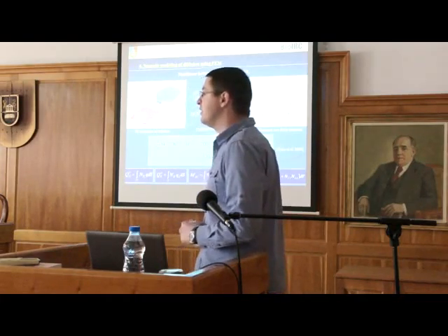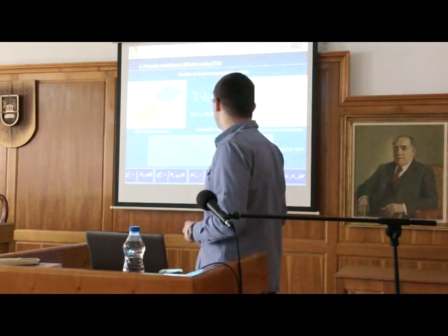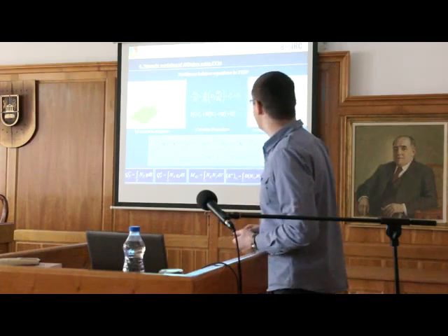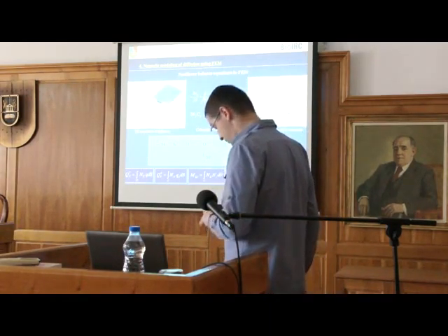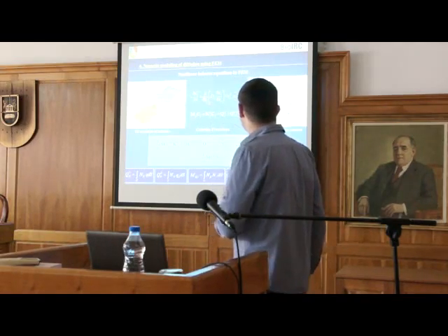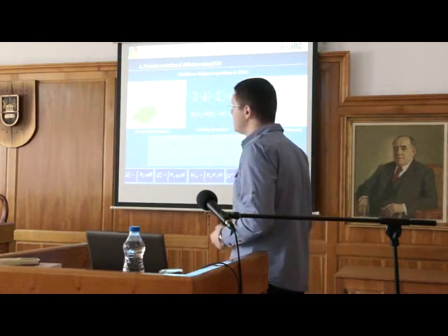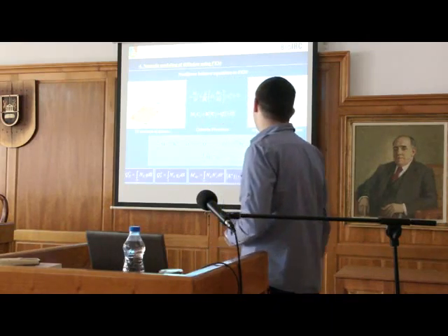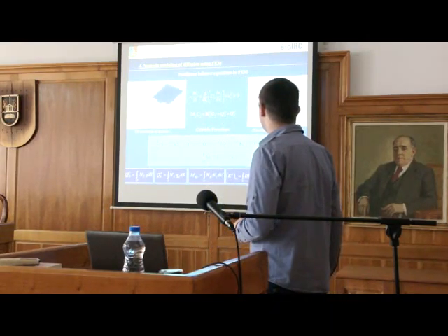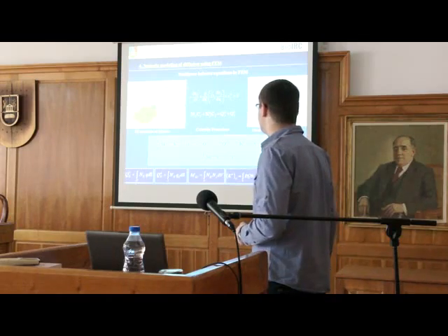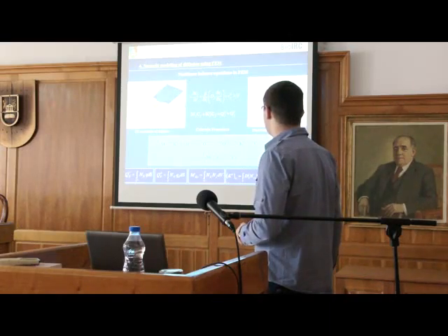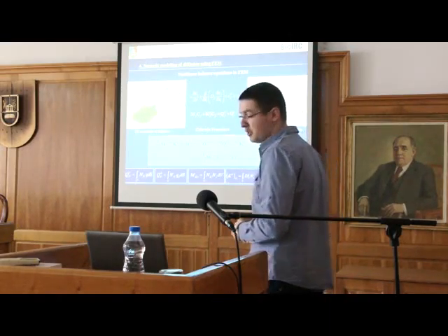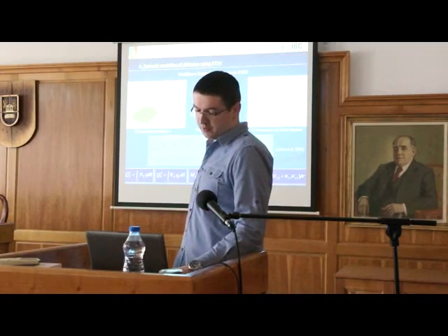Okay, we are using FEM. These are just some basic relations. So we started from the mass balance equation, and after that we use the Galerkin procedure, and we transform this mass balance equation into an iterative incremental procedure, and these are just parts of the matrices in the equations we are using in our software for numeric modeling.